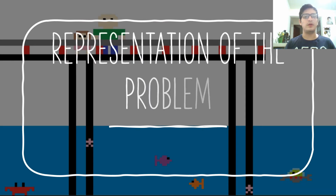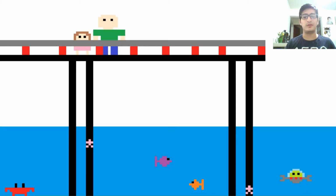We're going to show you a graphical representation of our problem. We have a pillar in a dock that will be in constant contact with seawater. Chlorine will provoke corrosion with time, and we want to calculate the concentration profile inside the pillar. We chose 50 years because diffusivity in solids is too small, so to be able to see a big change, we searched the useful life of a concrete pillar, and it was approximately 50 years.